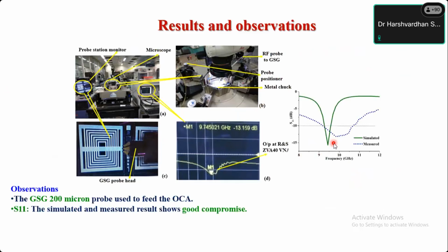So these are some results, right? One of the things is that we cannot use a simple microstrip antenna-like feed here. You can see that is another difference when we design from the normal antenna to the simple on-chip antenna. Here we are going to use a CPW feed.